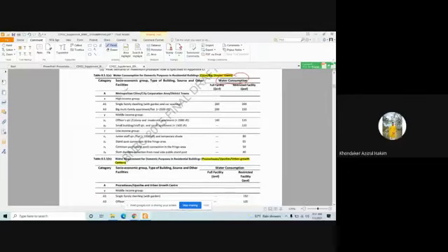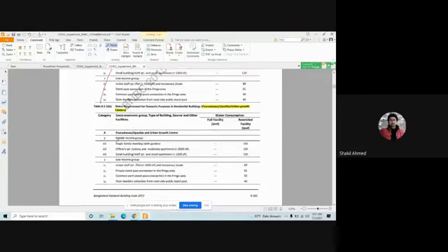Yes, sir. So metropolitan city, city corporation area, district town, high income group, single family dwelling. Do you see single family dwelling? With full facility, they produce 260 liter per capita per day. With restricted facility, they produce 200 liter per capita per day, and it varies for different types of facilities.